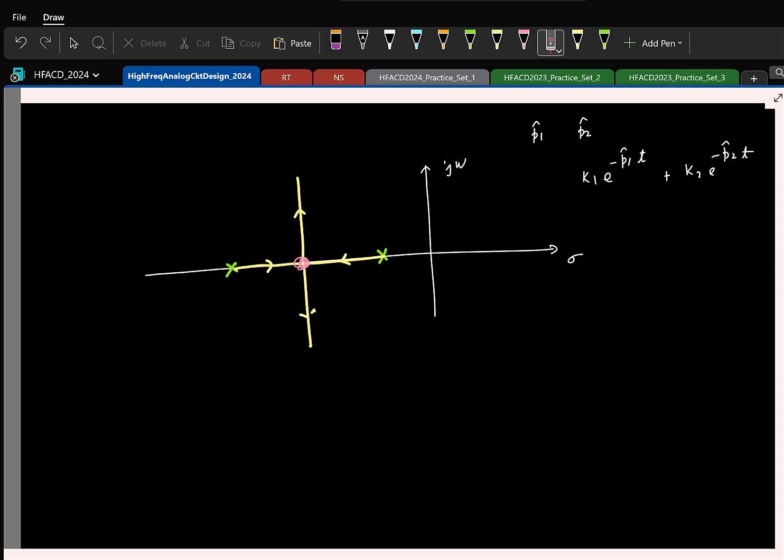And what kind of damping is that? For a second order system, critically damped. Hopefully you guys remember that. That's where both the poles are at the same location. So if they are, let us say, apart like this, what kind of damping is that? They are real but not equal. It's called overdamped, as you know.